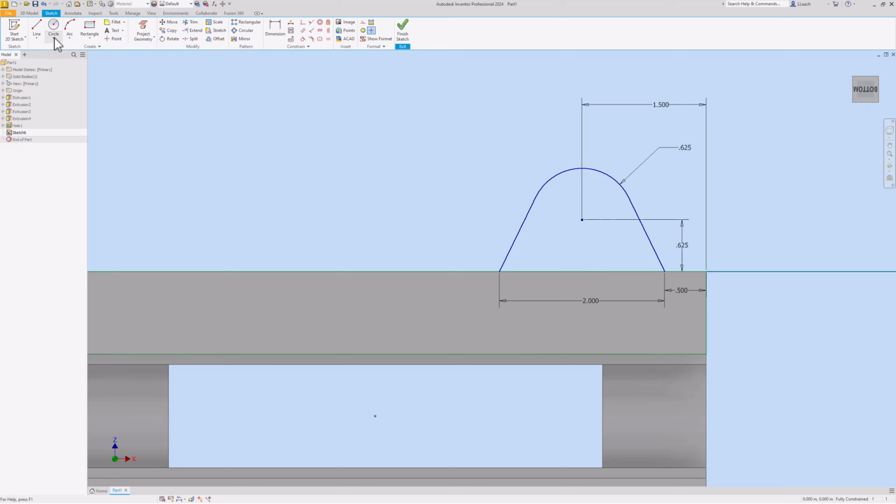Now I'm going to draw a circle from this point, and that's going to have a diameter of 0.375. 0.37. Nope, that's not right. I'm in radius. See, that's what I'm talking about. I'm giving it the radius, so I know that looks kind of big. So what I could do is double click this. I could say I want 0.375 divided by 2 to get my circle smaller like that. So let it do the math for me.